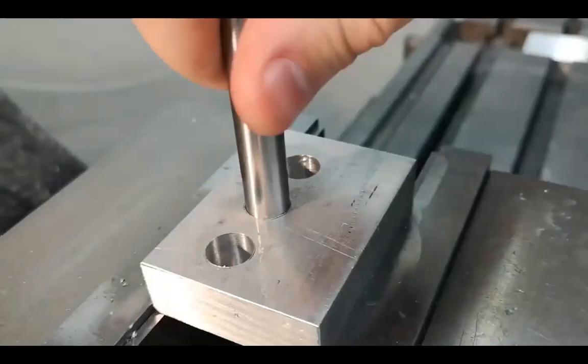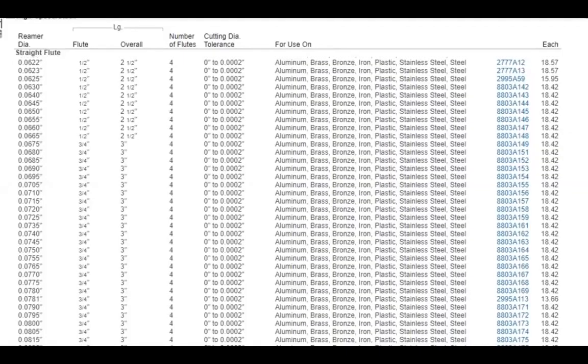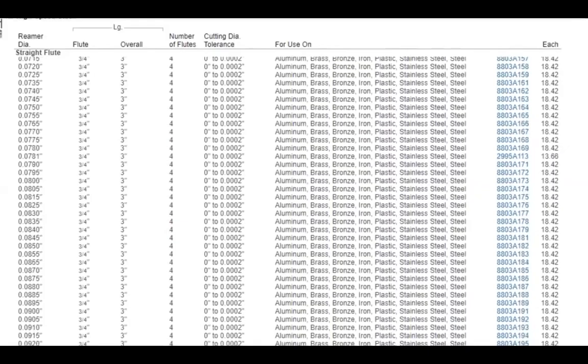Because you bought the dowel pins and have no control over their tolerance, this is called a shaft basis fit. So the challenge is now to decide what size reamer to use to make sure that all the dowel pins fit properly.